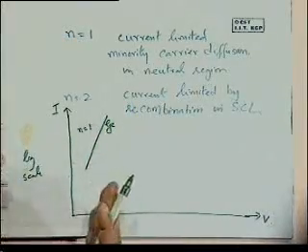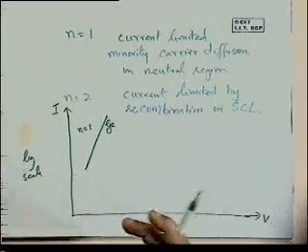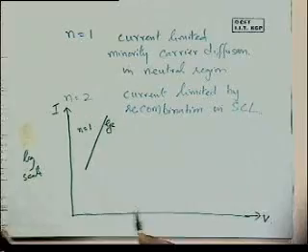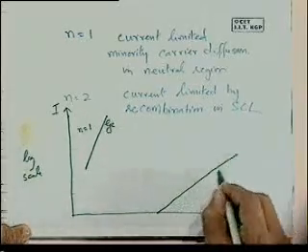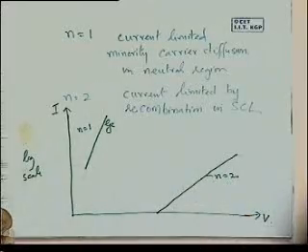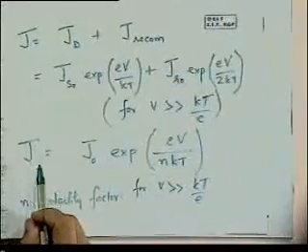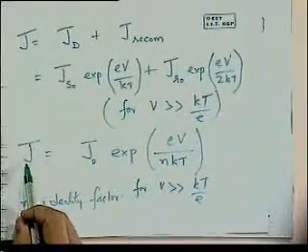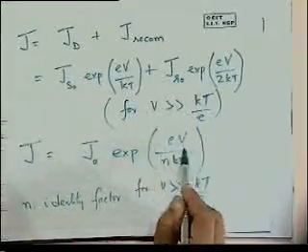That means in germanium PN junction diodes, the current is limited by the diffusion of minority carriers. On the other hand, for gallium arsenide, we will see something like this with N is equal to 2. If you look back at the previous equation, you will realize that if you were to plot the log of this versus V, N is part of the slope there, right?